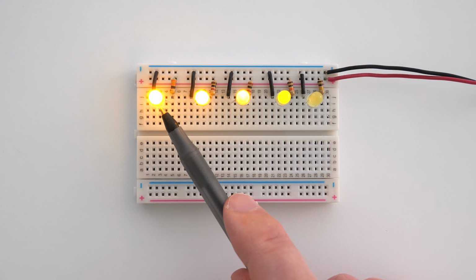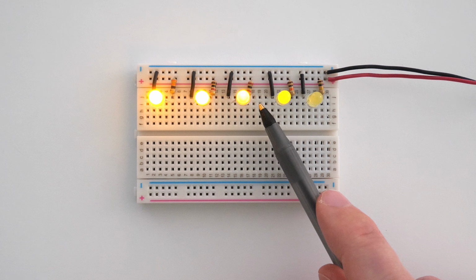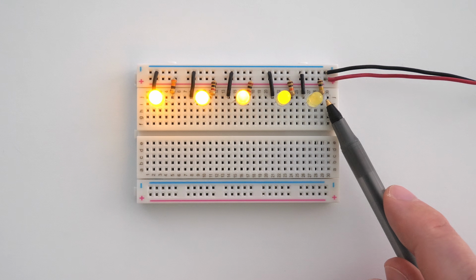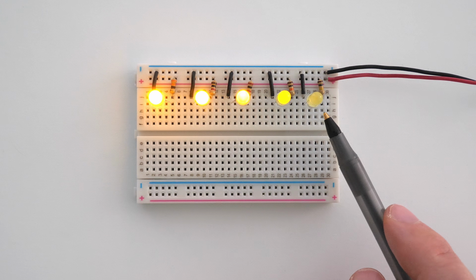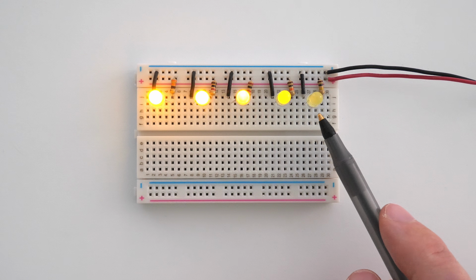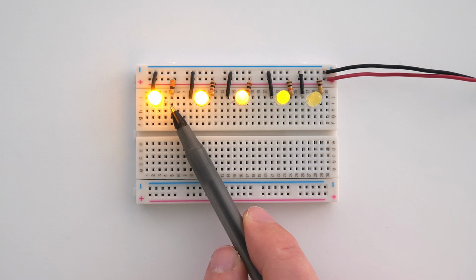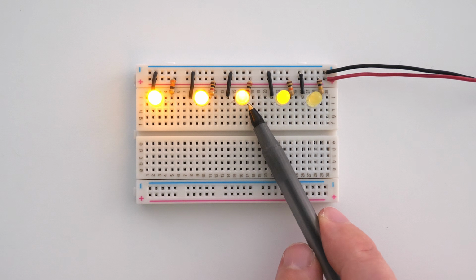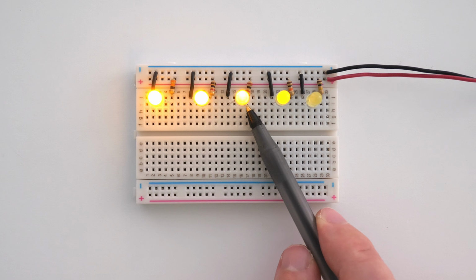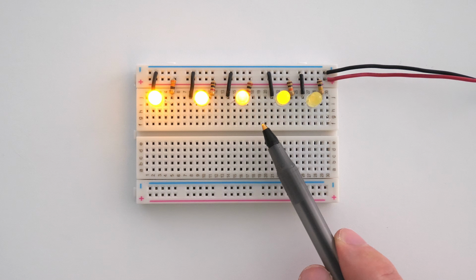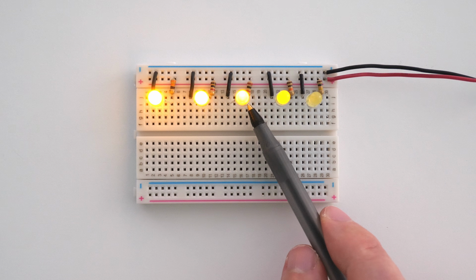It's actually so bright that it's kind of obnoxious in the camera, which is why I try and stay away from low resistor values. I typically try and use resistor values around 2K because you can tell that the LED is on, but it's not super bright. If you go to this 100K resistor, this LED is on, but it's just so dim you can barely see it. For all of the digital logic gates in this video, you can actually use resistor values anywhere from 330 ohm to 2.2K, and everything should work as expected. If you want the LED to be a little bit brighter, you can use a lower resistor value, and if you want the circuit to be a little more power efficient, you can use a larger resistor value.